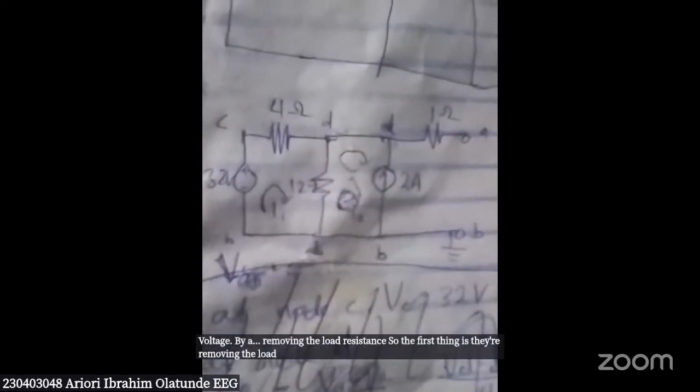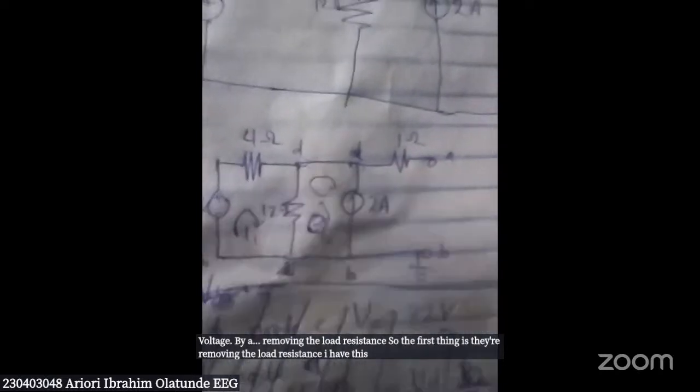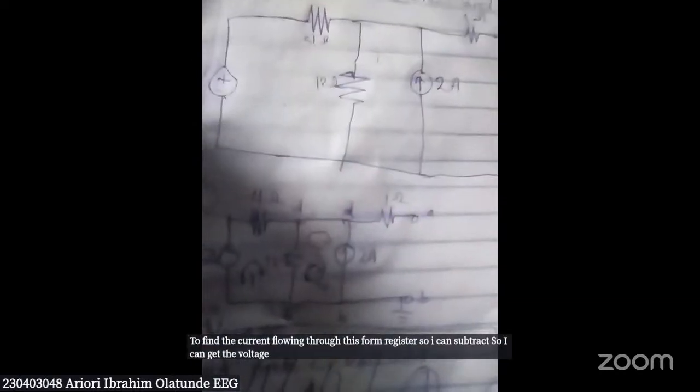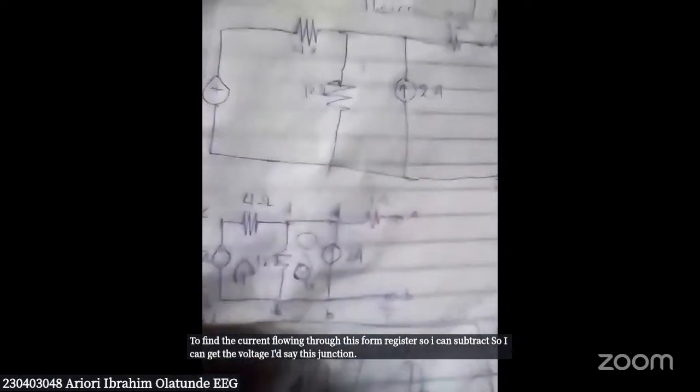So the first thing is removing the load resistance. I have this, and using mesh analysis to find the current flowing through this 4 ohm resistor, so I can subtract it so that I can get the voltage at this junction, because I'm trying to use this loop.